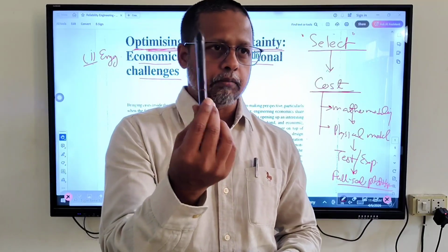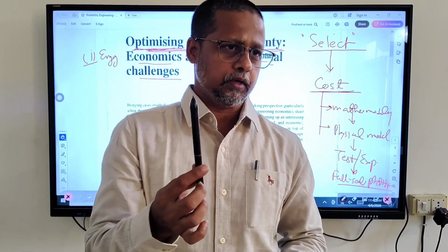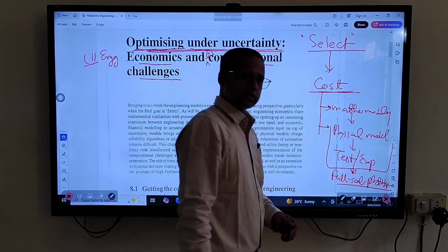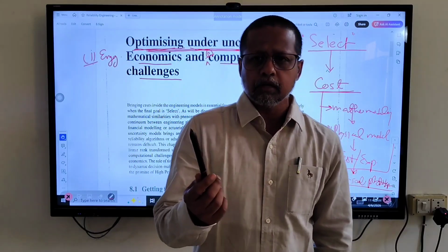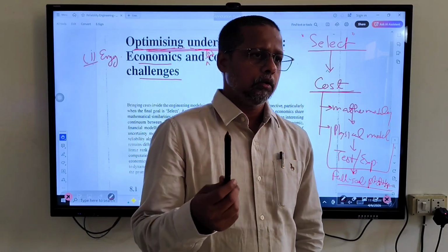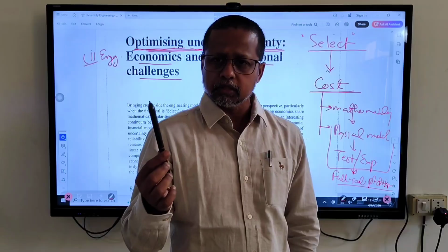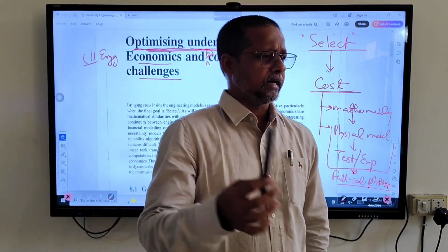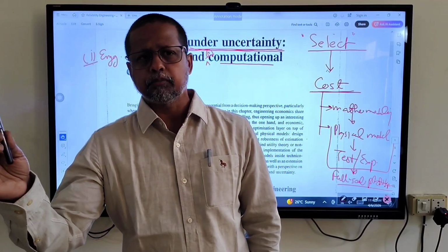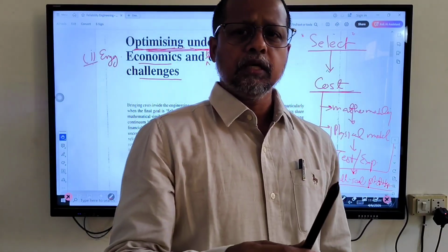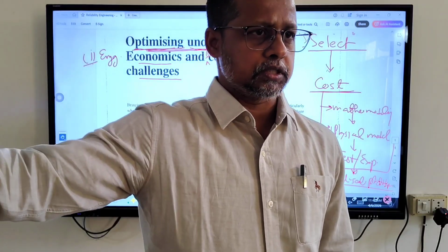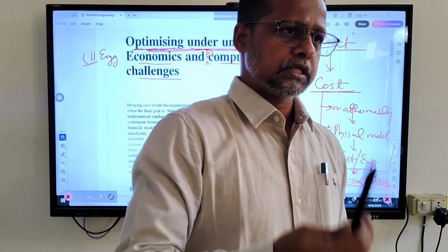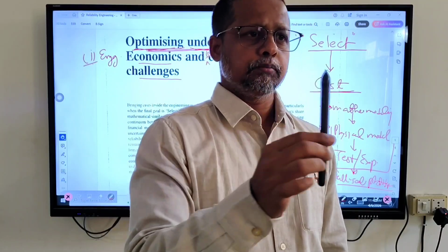But as far as this small commercial application is concerned, I don't need to go for that line. Probably this much level of validation is more than sufficient. If it is a cheaper product, as I have already told you, an industry that is going to make n products will test some 2, 3, 5% of products randomly. If those 3% or 5% of products pass their parameters, they pass all the n products, 100% as a batch, to go for commercialization. And for a little more sophisticated product, they go for a per unit product test.